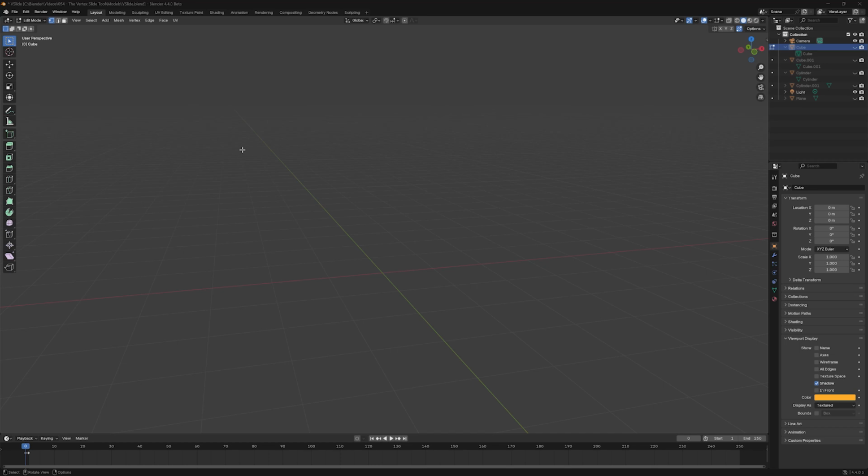The Vertex Slide tool in Blender allows users to slide a vertex along any edge to which it is connected. This tool is particularly useful when adjusting the position of vertices without altering the overall shape or topology of the model. It appears in the same grouping in the toolbar as the Edge Slide tool, and for good reason, since both tools share most parameters and keyboard options.